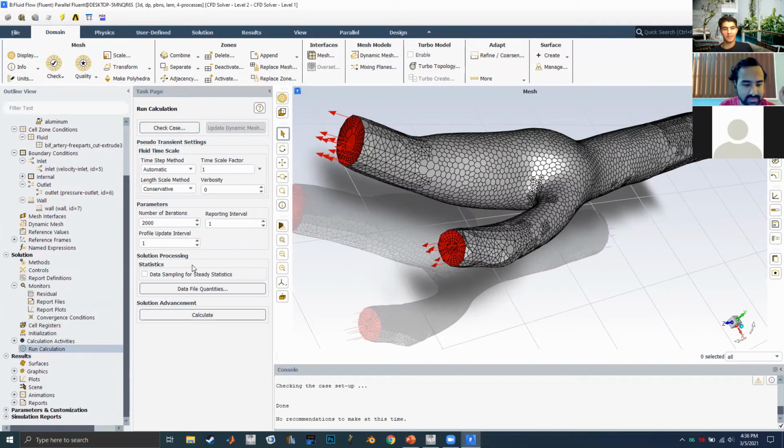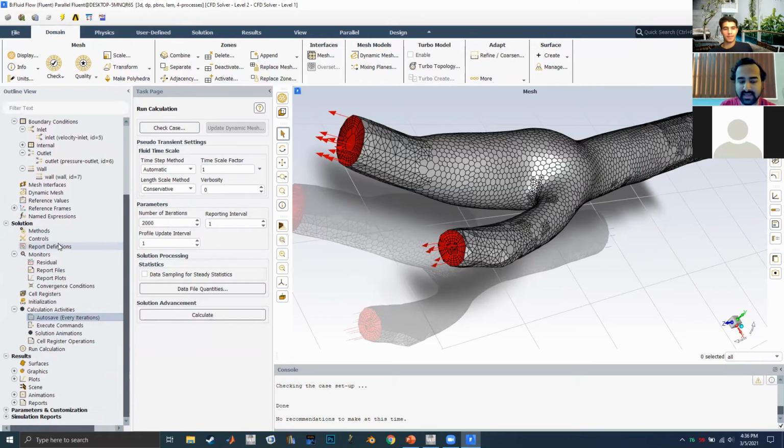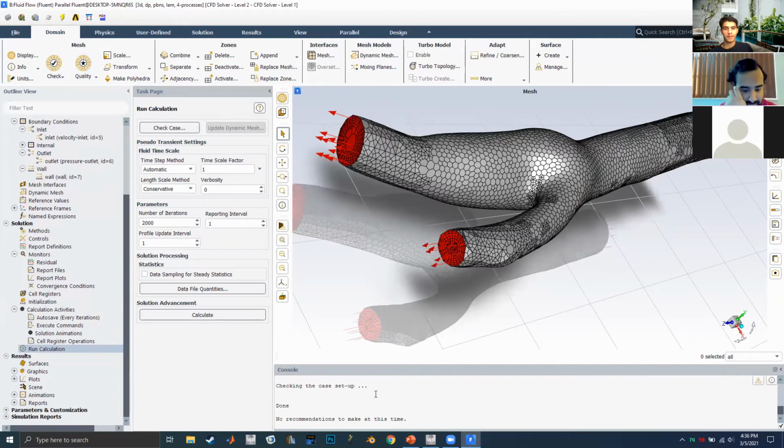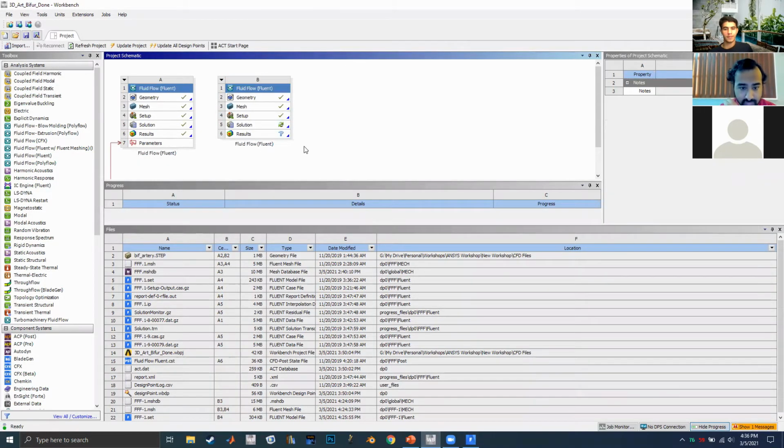I think that's it. If we were doing a transient analysis, we could have also done some time statistics, and some auto saving of quantities per time step. But because this is steady state, whatever final solution we get is the final solution, just a single time point essentially. So now I think we're ready to actually run our model. Give it a quick save as well. So Control S. All right, give it another save.